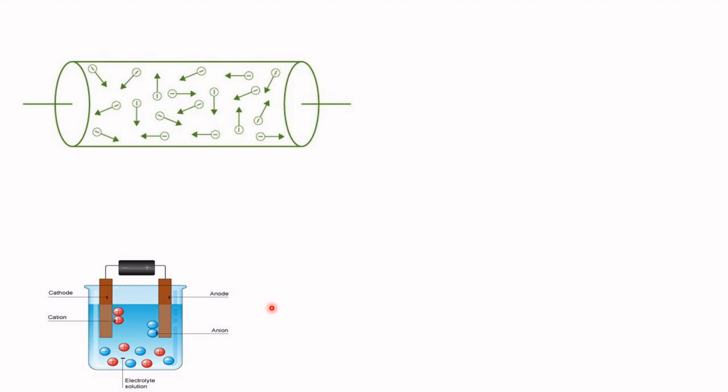So in general, when you take a dry formation, which is completely dry, something like a packed rock or an igneous rock, the resistance will be high. All the rocks and soils transmit the current due to the presence of water in the pores. But if the formation is dry, then the current passage will be less. That means the resistance will be more.